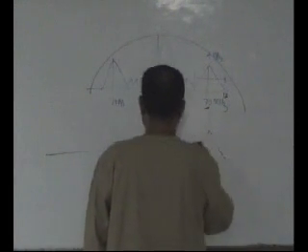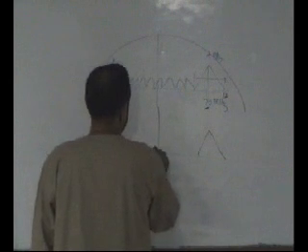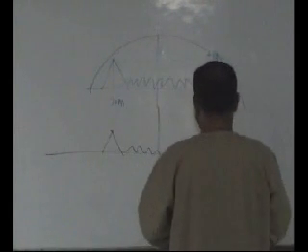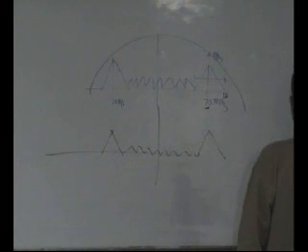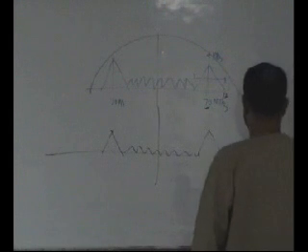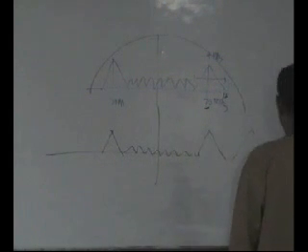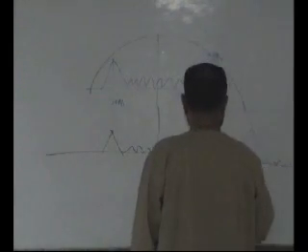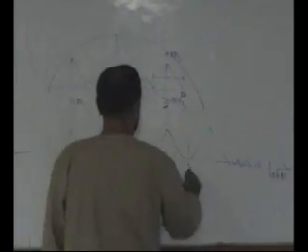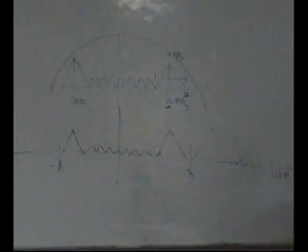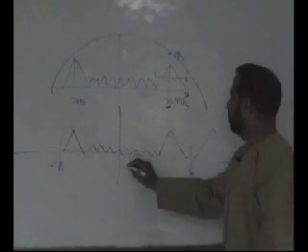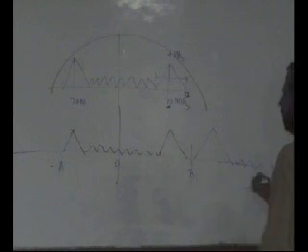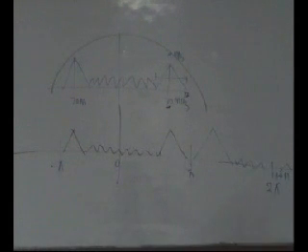So you get this here, and all this noise here, and then copies of it. So at 144 megahertz, you will get a copy, and this is your half the sampling frequency. So this corresponds to minus pi to pi, and these are the copies, right? At every 2 pi you are going to get a copy, and at minus 2 pi you are going to get a copy. We know this, right?